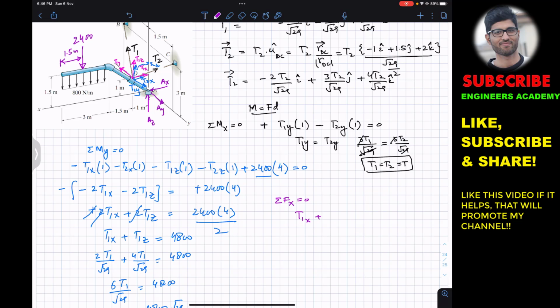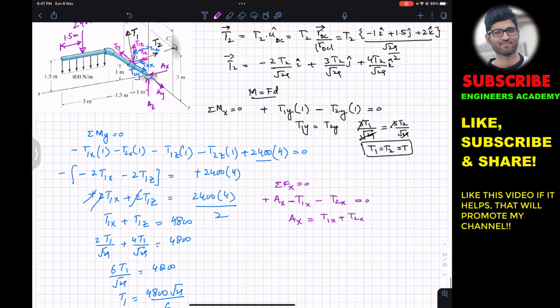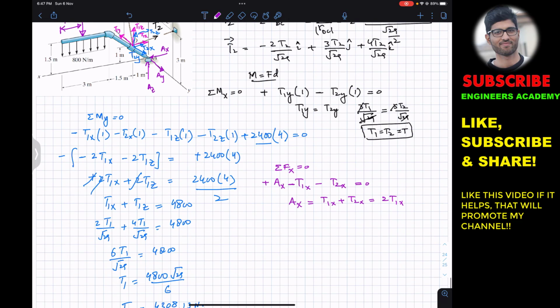The t1x and t2x are acting in the negative x, so we write minus t1x minus t2x, and Ax is acting in the positive x, so plus Ax, equal to 0. So Ax is equal to t1x plus t2x, which is 2t1x since t1 and t2 are equal. So Ax is equal to 2 times t1x.